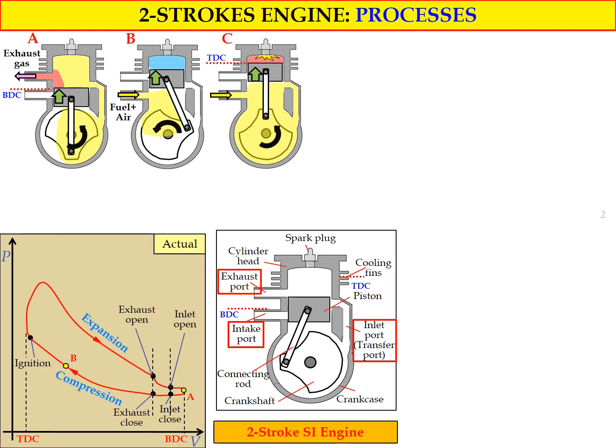In this case, no exhaust gas or combustion product is released to the surrounding, and no fuel plus air mixture enters the combustion chamber. However, the fresh fuel plus air mixture will fill throughout the crankcase, and stand by to enter the combustion chamber when the inlet port opens to the combustion chamber area.